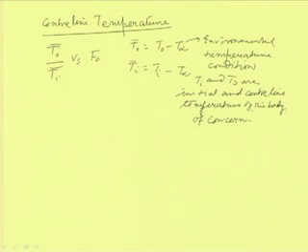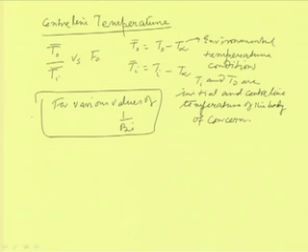T0 bar by Ti bar is the dimensionless center line temperature, and Fo is again a dimensionless quantity called the Fourier number, and these variations are there for various values of 1 by Biot number. So, for various values of Biot number or 1 by Biot number, the center line temperature plots are available for all three geometries: flat plate, long cylinders or spheres.